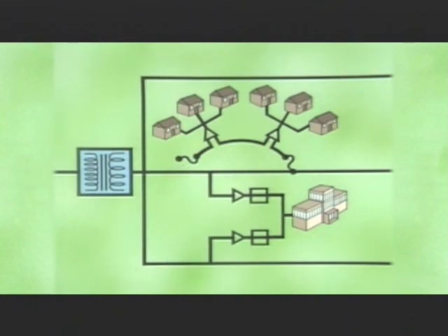It works like this. Taps from two feeders run to separate distribution transformers. One transformer is connected to one feeder, and the other transformer is connected to a second feeder. The secondary side of each transformer is connected to a secondary bus. From the bus, a service drop supplies electricity to the customer, in this case a hospital.